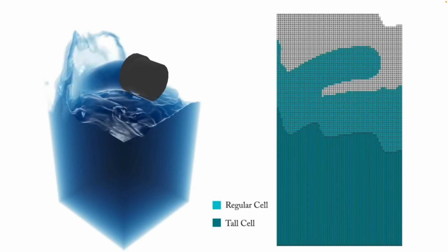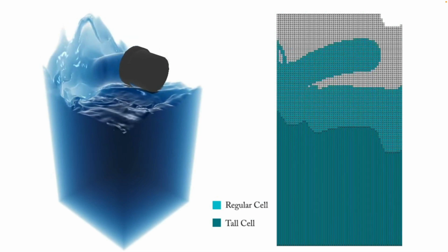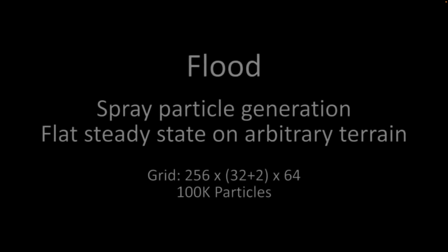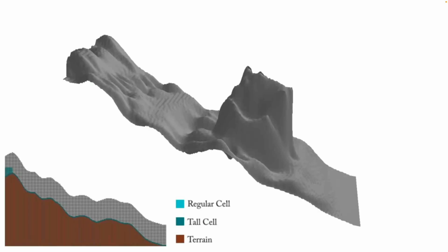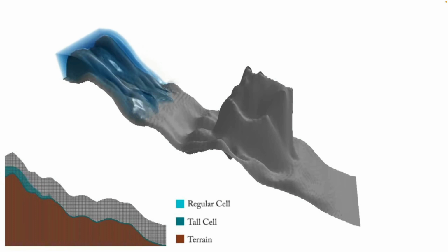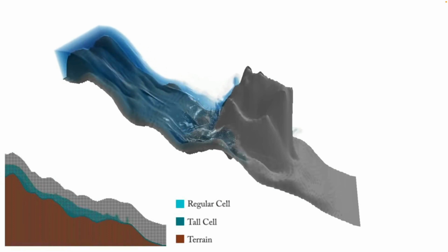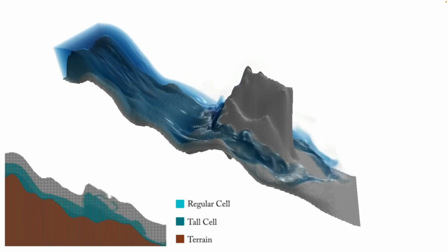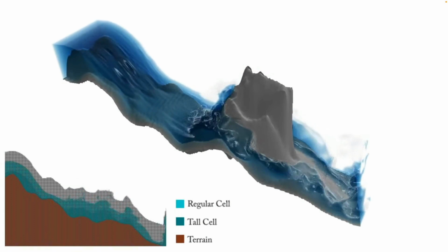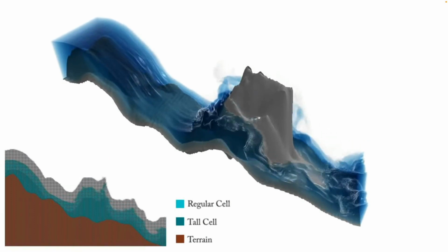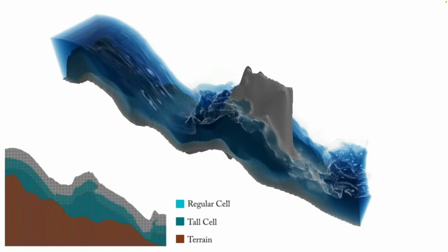Or alternatively, you could look at the behavior on a static grid, which is what this right-hand side is showing, and you can look at the fluid coming in from the right-hand side of that grid, coming out of the left-hand side of that grid. There's a mass balance there clearly, and also there's a momentum balance that you could track. And so these are relatively sophisticated calculations, as you can imagine.